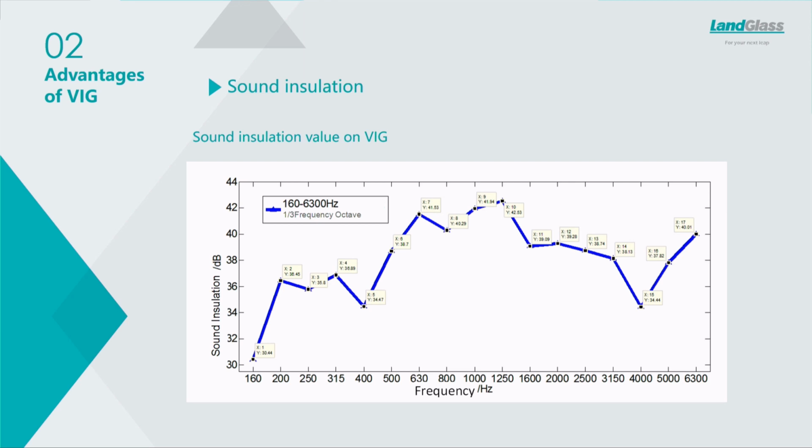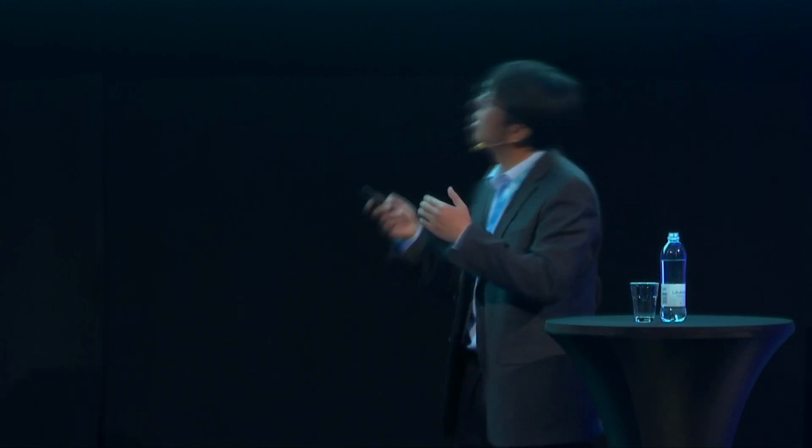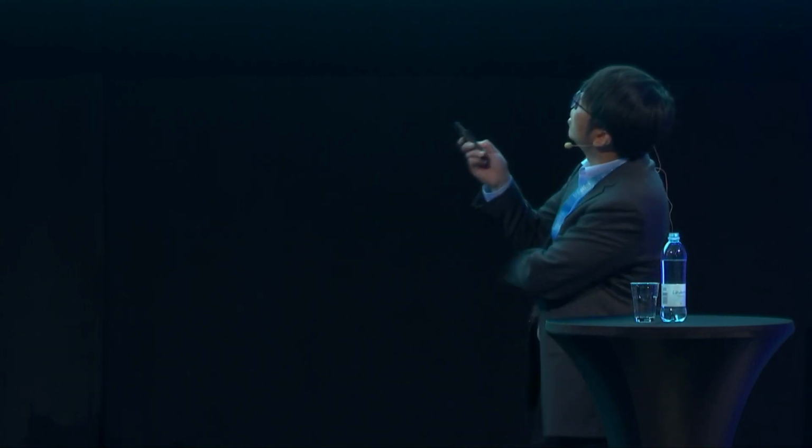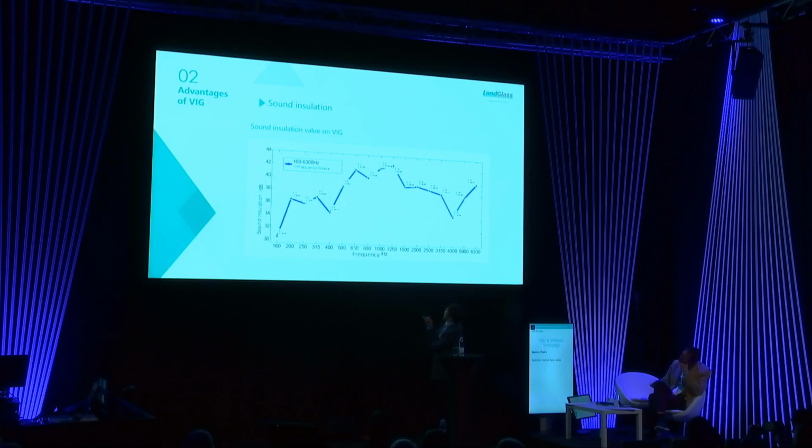It's because during the low frequency, it will trigger the glass to vibrate, and the vibration will be transferred by the pillars. And when the frequency is higher than 500, you can see it actually gives you more sound insulation.